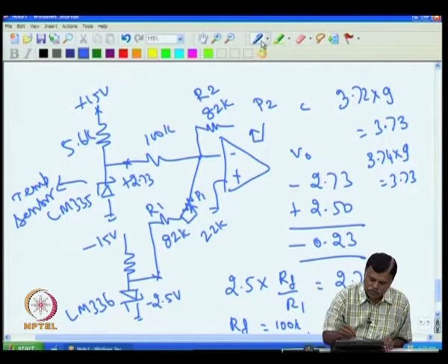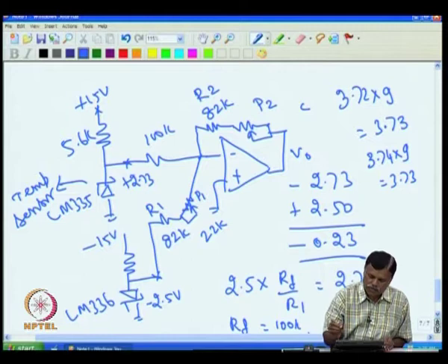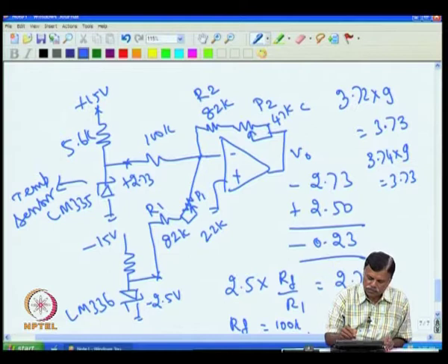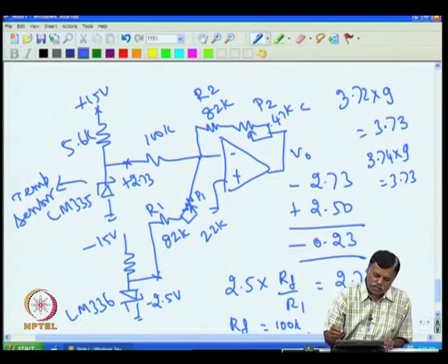Okay, what I do is I take P2 a little higher, so that my adjustability is better. So, I can put for example P2 as 47 K, and then this is fixed 82 K. So, I can adjust now up to 129 K at one side when the potentiometer is maximum; when the potentiometer goes down, I will have 82 K. So, now what I do is I will put this one at 100 degree C and adjust P2 to get 1 volt.